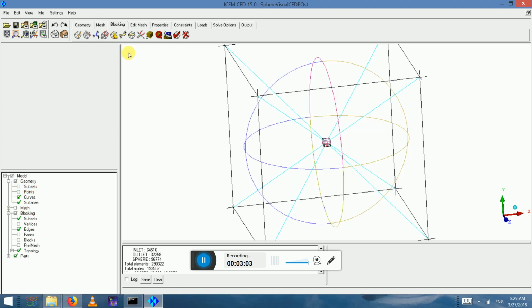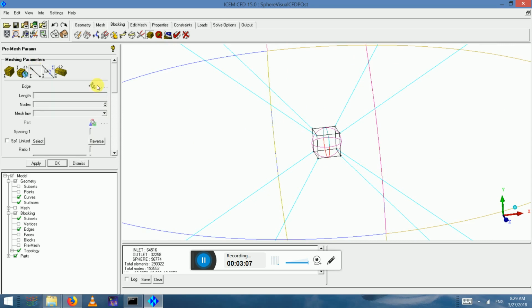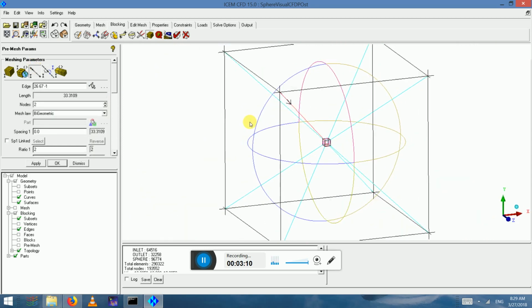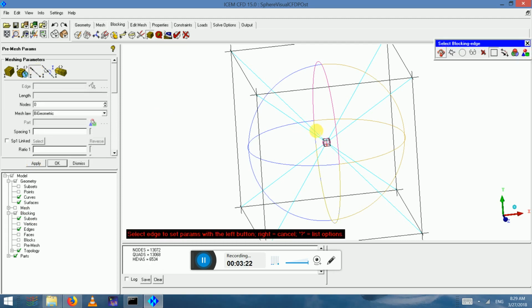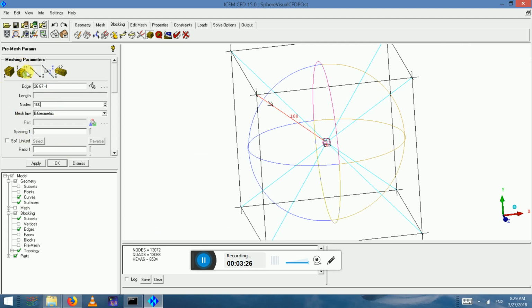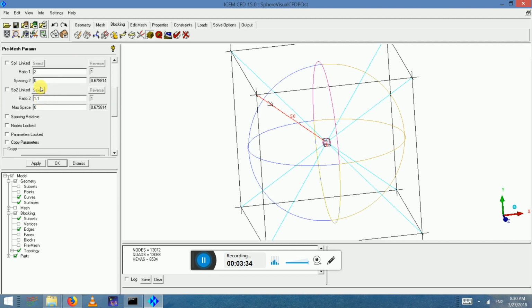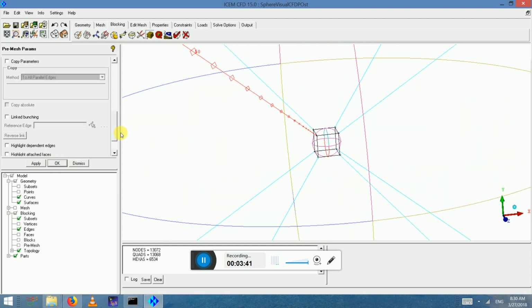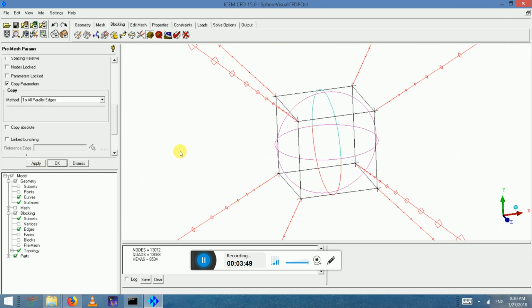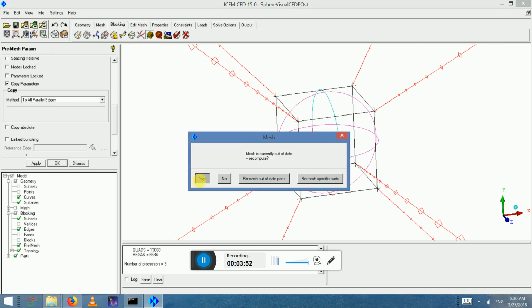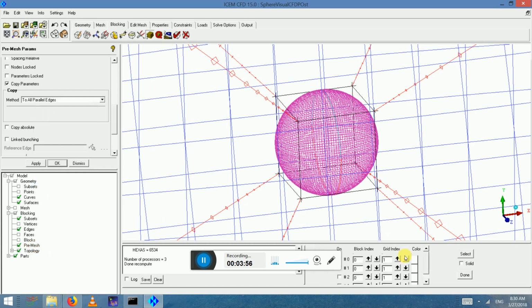It's not too bad, but just to refine this mesh, actually we haven't got any grid nodes here, so what I'm going to do is rescale it, 0.5 and 0.5, and then use some grid nodes here, maybe 100, a bit too much, 50, and use the ratio 1.2 or 1.1, and give some small spacing close to the wall, according to your Reynolds number and so on, but I don't have a particular Reynolds number of interest for this domain.